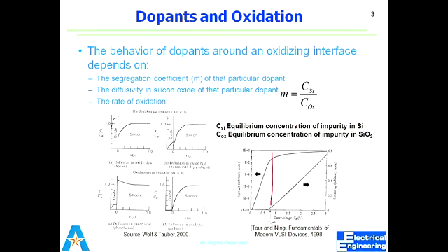That's why I say that I'm using dopant and impurity as alternative words, because if you have a silicon crystal, anything other than silicon will be considered an impurity. But if we have introduced that impurity intentionally, we say that it has been doped. So dopant is also a beneficial impurity that has been introduced intentionally.